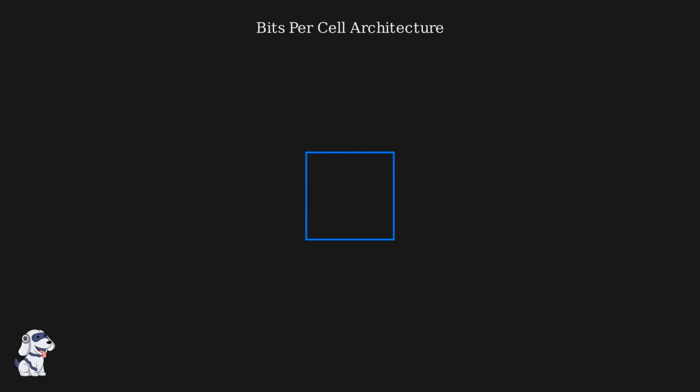In SSD technology, we increase capacity by packing more data bits into a single memory cell. This is achieved by defining distinct voltage levels within that cell. The SLC architecture stores 1 bit, 2 levels. As we add more bits, the cell requires finer voltage control to distinguish between these increasing states. The MLC architecture stores 2 bits, 4 levels.